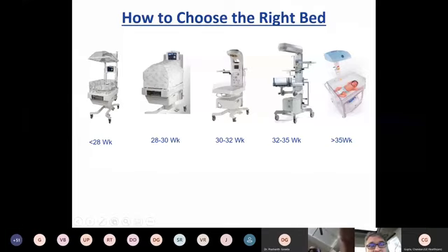So we need to ensure it is done with an 8-tank pre-treatment process, where every process like degreasing and passivation goes through 8 tanks. If we do 8-tank, then the quality of the product is assured.